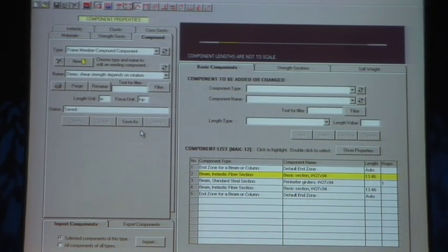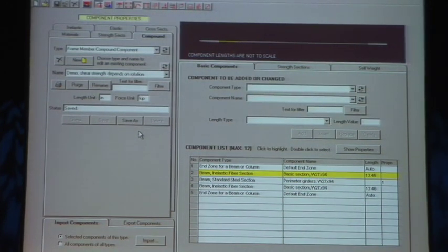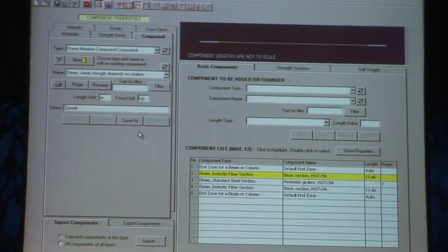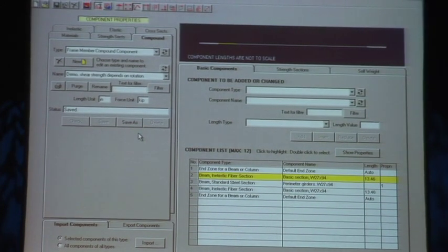So what it is saying is when you come to calculate the shear strength capacity at this cross-section, look at the current amount of rotation over this plastic zone. Using that rotation, go into the little diagram I had before, calculate the strength reduction factor in shear, apply that to the shear strength to get an effective, a reduced shear strength, and calculate the demand capacity ratio based on that reduced shear strength. It's an important effect.